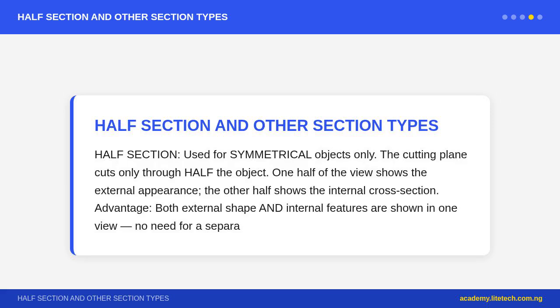Question 1. What is a sectional view and why is it used? Answer. A sectional view is produced by imagining a cutting plane slicing through an object, removing the near part, and drawing the cut surface. It is used to show the internal features of objects, such as bores, chambers, walls, and threads, more clearly than hidden, dashed lines can, especially when internal features are complex.